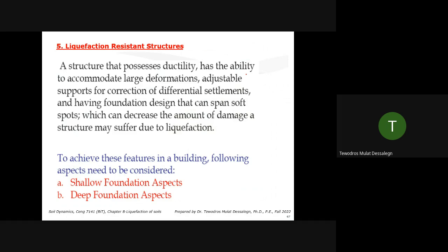Or introduce a shallow foundation, which is like a mat foundation. Covers a wider area, so the possibility of being inclination or being swallowed is little. Isolated foundation is probably the worst one when it comes to liquefaction. Isolated footing.